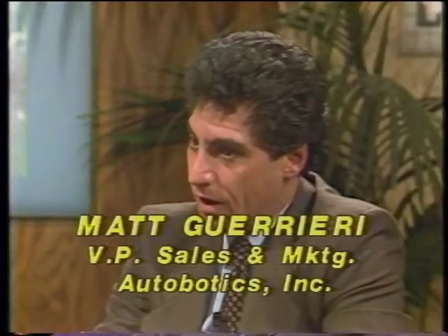I guess one of the differentiating factors in robots used in industrial applications of that sort is that you can build a very precise robot that would weld within a few millimeters of where it should weld, or you could use vision processing to figure out where the object is and manipulate it with very coarse mechanical devices. Yeah, or as David points out, putting the robot into a structured environment, such as an integrated work cell, where the work is presented to the robot in such a way that it doesn't require the extreme accuracy or sensory capability that some of the anthropomorphic machines currently require.